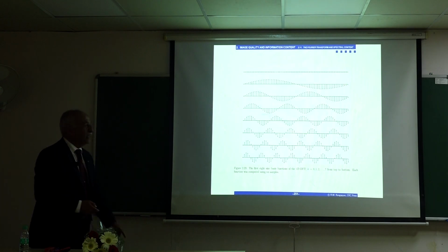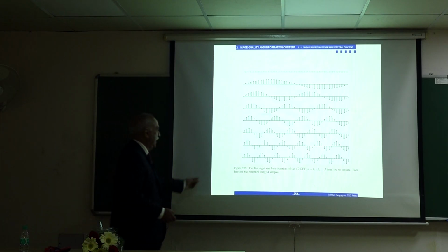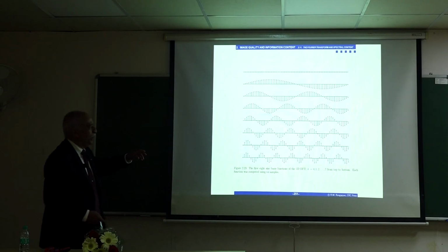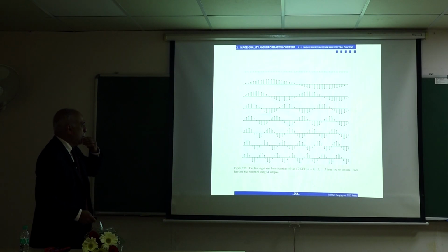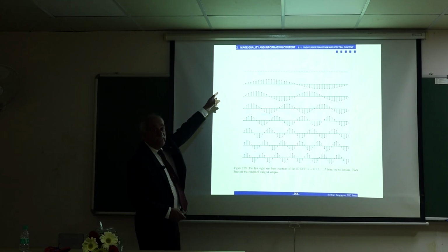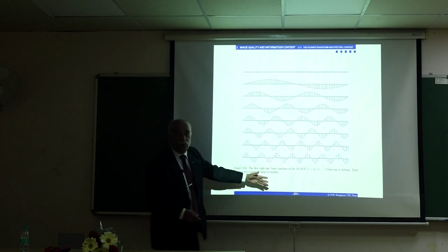So this is what 1D sinusoids look like. This is the first 8 sine basis functions of the 1D DFT, k going 0 to 7. I computed each one using 64 samples. So first is DC, 1 period of sinusoid, 2 periods, and so on.